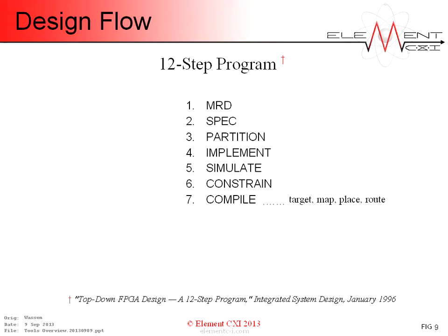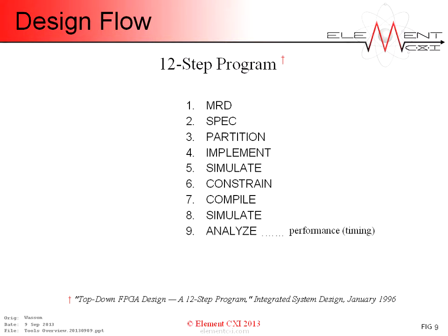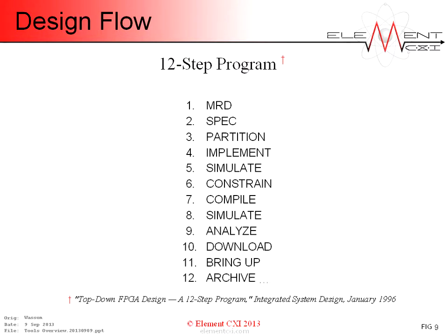targeted devices, simulate gate-level results to ensure conservation of functionality, analyze timing to make sure performance targets are met, download the bit stream into a device on a test bench board in the lab, bring it up, the polite euphemism for debug, because things rarely go right the first time, and finally, archive any and everything needed to recreate the project.